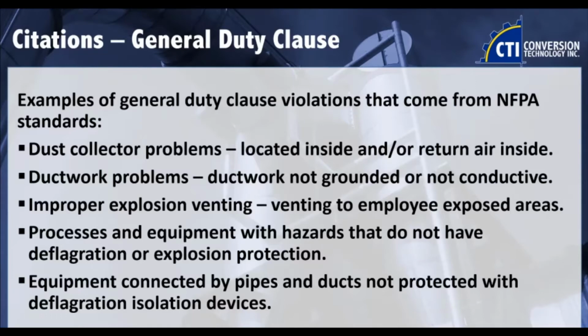I know a lot of you in Ohio might do that during winter to save on heating costs. Well, that can be done, but NFPA has a very specific requirement for that to happen. And for those of you that know, it's NFPA 652 9.3.4.3.3.